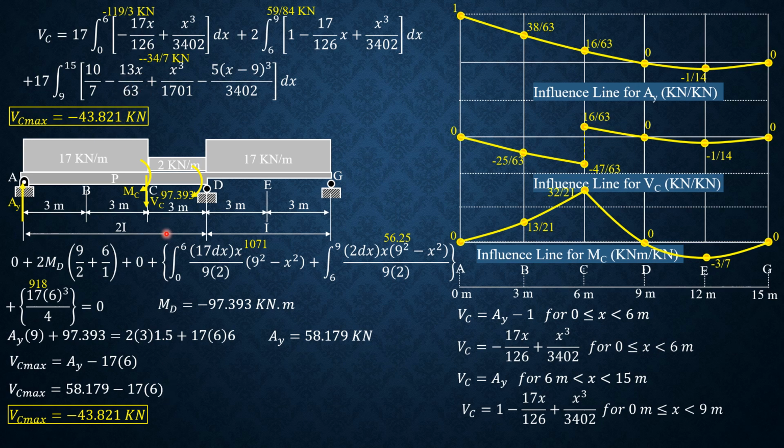But for me, it's easier if we just position the loads and analyze it by the available method, 3 moment equation or slope deflection equation, whichever is easier for you to apply. But for me, it's 3 moment equation, the better way. But you might forget this expression, so you have to derive this again, the value of 6A1A over L1I1 or 6A2B over L2I2.